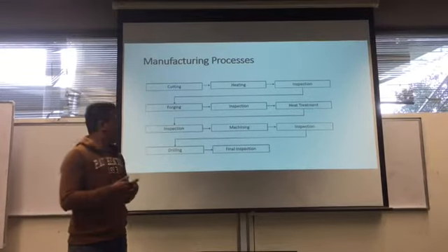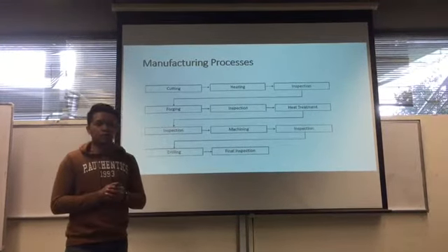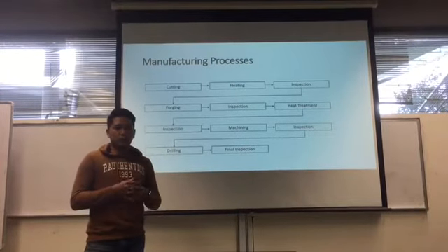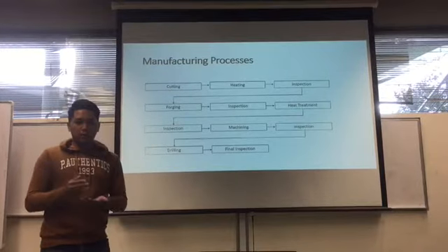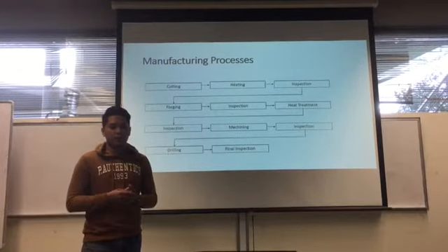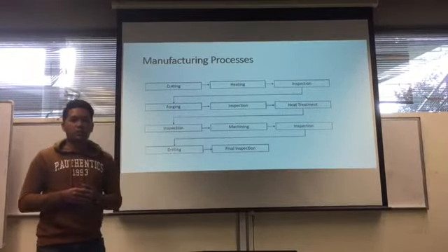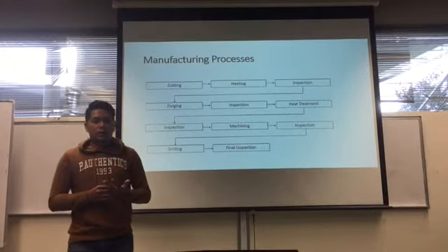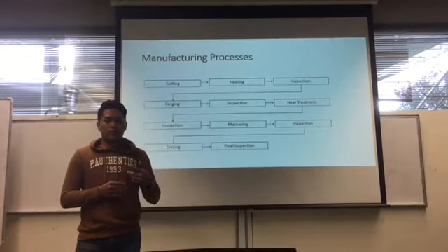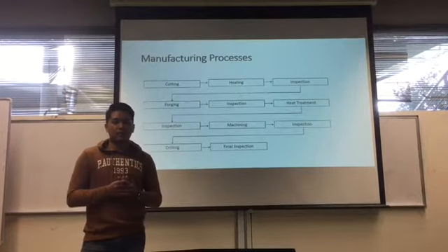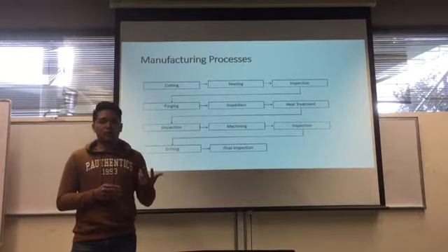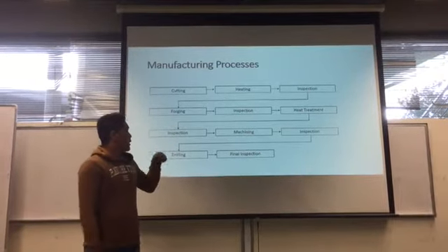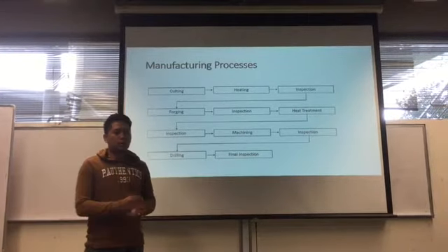For the forging process, we will use the cold forging method, which means the flange will be forged below the recrystallization temperature. The steps involved in cold forging start with the metal being placed into a die that is attached to an anvil, and then the metal is hit by a descending hammer and forced into the die. After the forging process, again we will inspect the product,